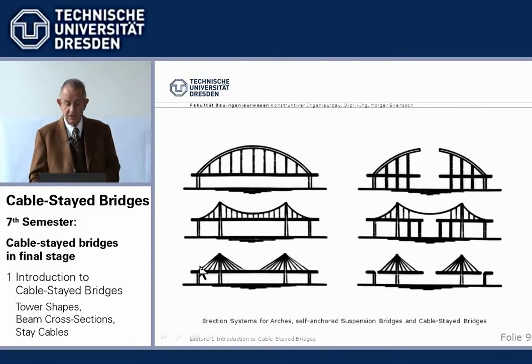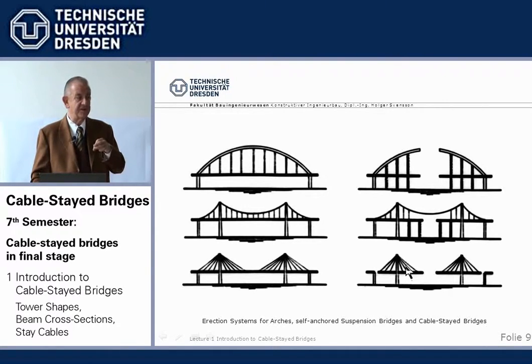It is different for cable-stayed bridges. Cable-stayed bridges carry their loads in the cables and back here in compression in the beam. And when we have initial systems, we free cantilever them to left and right, and we have the same flow of forces in these construction systems as we have at this location in the final stage.